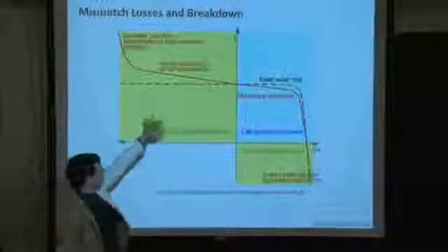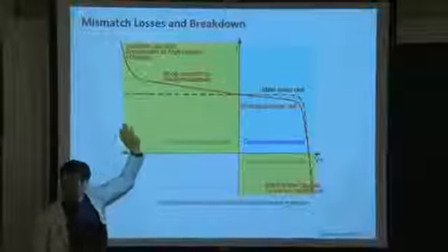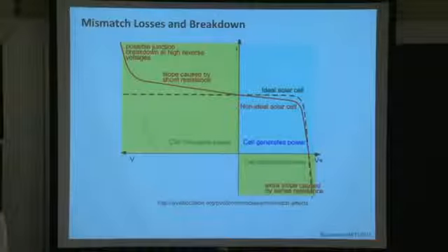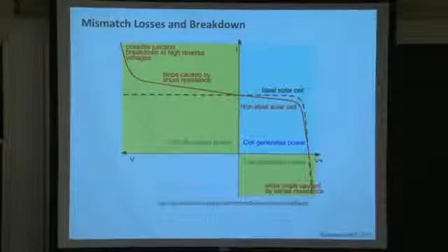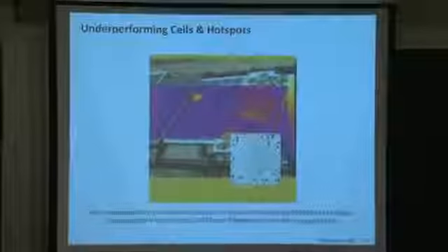If you reverse bias your devices, you can enter what's called a breakdown regime, that essentially is driven oftentimes in a real solar cell by isolated points, say, weaknesses in the PN junction where current is going to flow, and that leads to the hotspot failure I just mentioned.